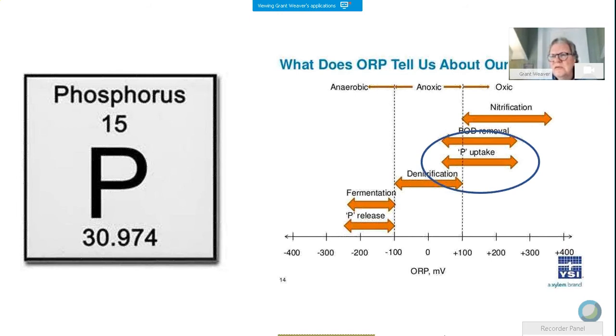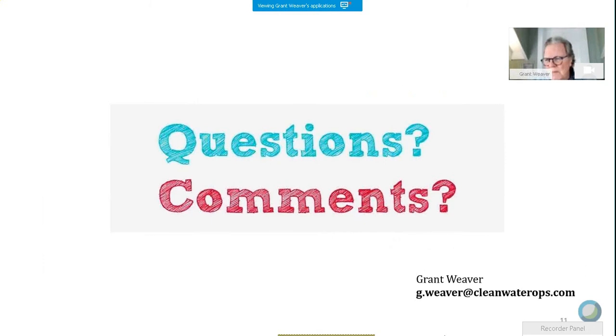The difference is the phosphorus-removing bacteria are more sensitive to pH, so it's theoretically possible to have a pH, say, of 6.7, something like that, 6.6, good enough to support ammonia removal, but not good enough for phosphorus removal. Otherwise, the conditions that would support ammonia removal generally will support that last step of phosphorus removal.